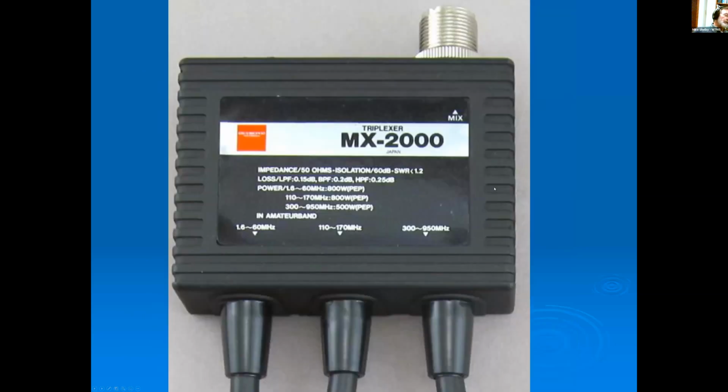So this is a triplexer. Sorry, the focus isn't real great on this, but this is a cool unit where if you wanted to, this could connect back to your transmitter. You have down here on the bottom these chunks of coax that come out that have PL259s on them. The leftmost port takes care of all your HF through 6 meters. Middle one takes care of your 2 meter stuff. The one on the right side takes care of all 440.